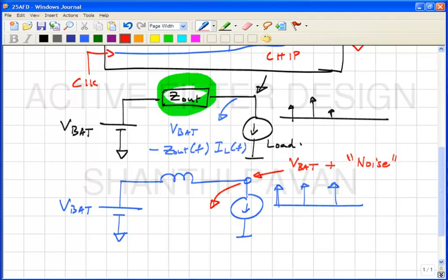Well, when we really don't know the exact statistics of these pulses, you might as well say noise, right? In principle, if you know the input to the DSP, you should be able to predict what current it will draw. So that way, it is indeed deterministic. But as far as the filter is concerned, it's probably completely uncorrelated with what the filter is processing. So you might as well call it noise.